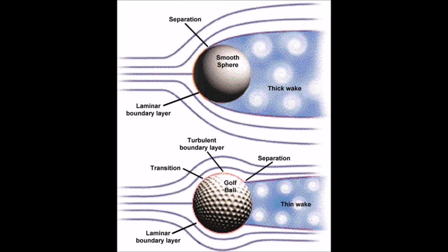This is a method of passive boundary layer control. Golf balls take advantage of this effect using a dimpled surface to control the boundary layer during flight. The dimples trip the boundary layer close to the leading edge of the ball, causing the rest of the boundary layer to stay attached to the ball longer. This culminates in an enormous increase in potential range across all club swinging forces. Golf balls are one of the many applications of controlling the boundary layer of objects subjected to flow.